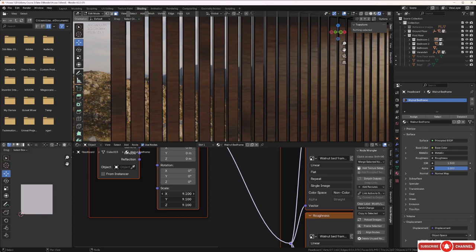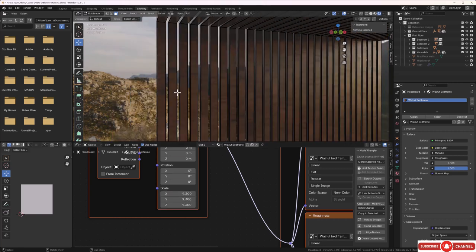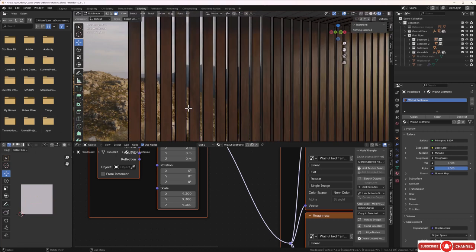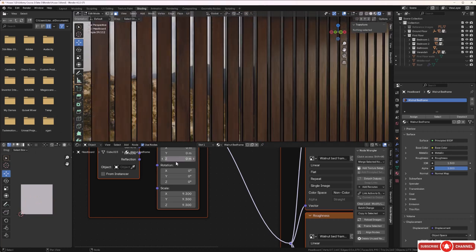And let's leave it something like that, because then also let's rotate the grain. So I'll press A for all, grab the UV map, press R, rotate 90 degrees, and press enter. And now let's try that again and see what we've got. And obviously that's better. So I'll do the same now. I'll just hover over the top arrow here, hold down the left button, drag to the bottom, and then just move it along until we get something that we're looking for.